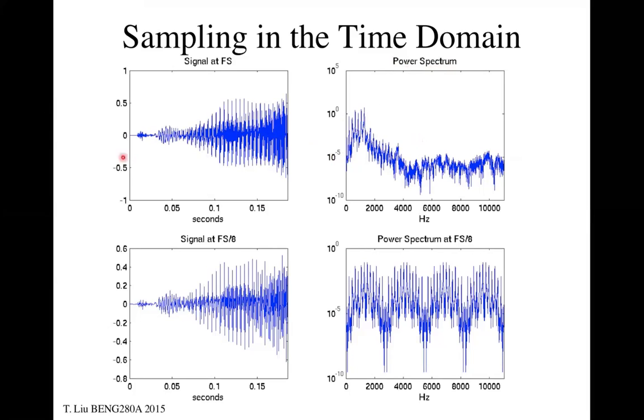So this is in time, and this is in hertz, or cycles per second, right? If I look at an interval, say, from 0 to 100 milliseconds, and I have 100 full cycles in there, that's 1 cycle per millisecond, so 1 kilohertz is the frequency component. So I come to my Fourier spectrum and say, okay, here's 1 kilohertz, and that would be the peak at that frequency.